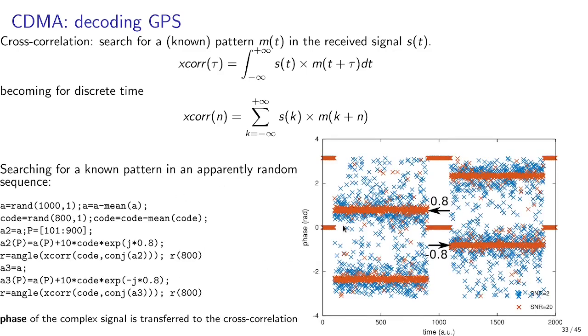But most importantly, if we add some phase offsets to the signal because the broadcast information is BPSK modulated, then this constant phase, which is not time dependent, will come out of the integral and will affect the cross-correlation in the same way as it affects the signal. Indeed, we will be able to recover the phase that was broadcast from the correlation phase on the receiver side.